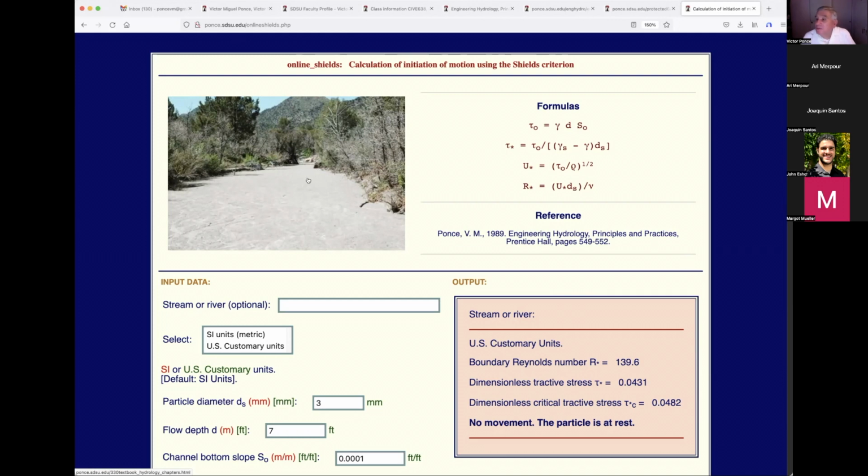And if the slope is steeper, like 0.01 or greater, it will have some cobbles. So when you look at a river, if you're experienced, you can almost tell the slope of the channel within a certain range. In this case, we're talking about a slope of 0.001, which is roughly 0.1%.